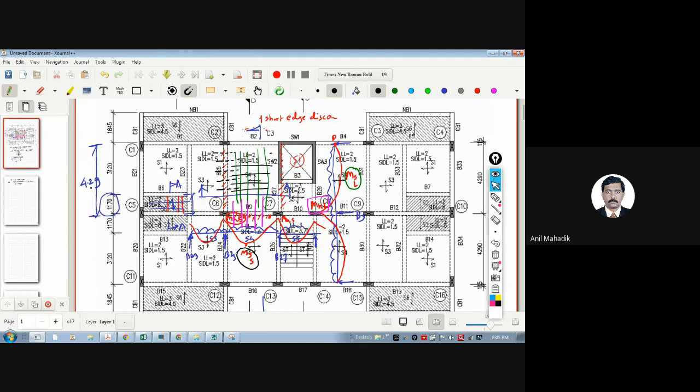And again here I will provide the negative support steel here, here, here, here. And as there is no moment at this point, I can ignore the steel here. But generally we provide minimum steel, as I told you yesterday, to avoid the cracks. So minimum Ast I can provide in this direction also, over the support. Over the support means top steel.